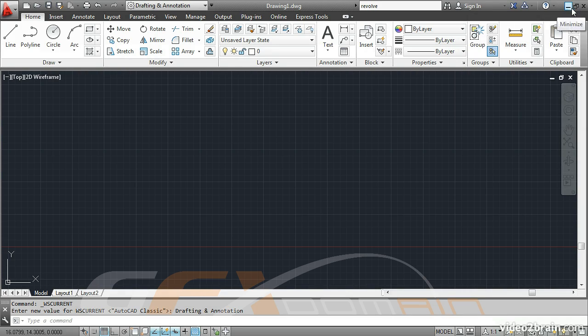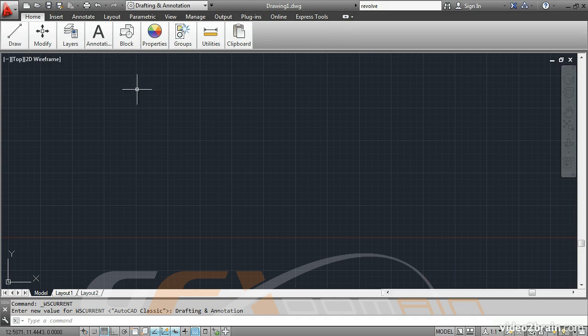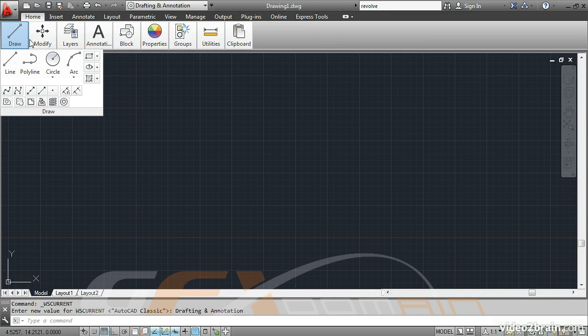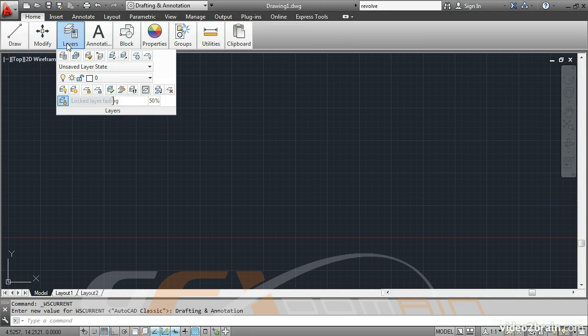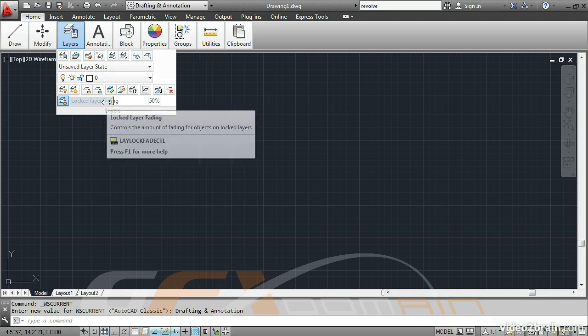These buttons refer to the application itself, whereas these buttons are specific to the current drawing. The ribbon can be displayed in many different ways. This is the full ribbon interface that we're looking at right now. Click here to minimize to panel buttons, and then each panel is represented by a larger icon. The same commands are located on these panels.